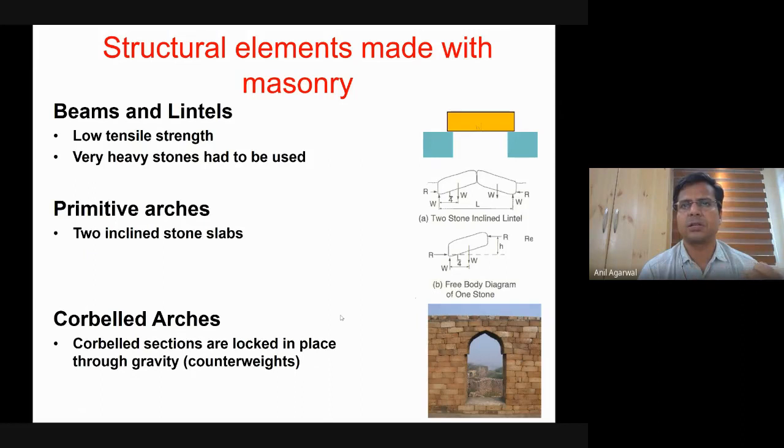But the problem with masonry is that almost all such materials, whether it is concrete, masonry, or mortar, all these materials, which are basically earth-based materials, have very good compressive strength. So you take a brick, you can apply the load of a truck on a brick and nothing happens to the brick, right? A truck's wheel can very easily pass over a brick and nothing happens. However, if you apply even 10% of that load in tension on that brick, the brick would very easily fail, right? And as you know, flexure is made of tension and compression. So part of the brick is in tension, and part of the brick is in compression. The part that is in tension would fail, and as a consequence, the brick would fail.